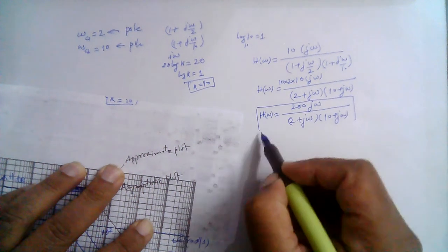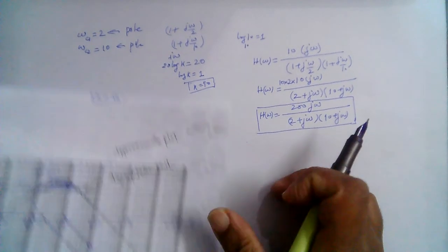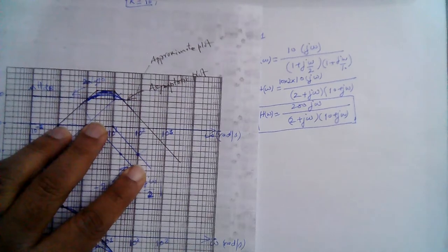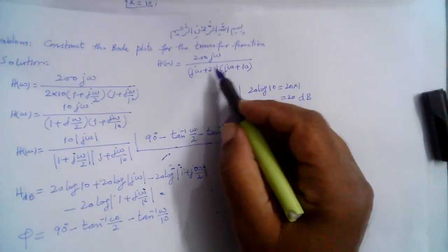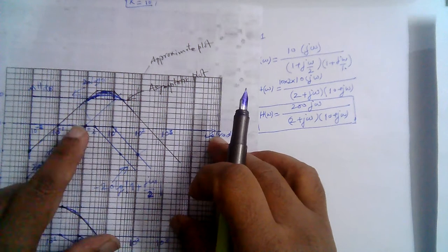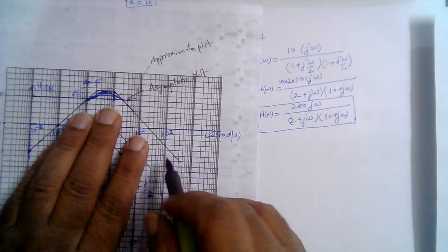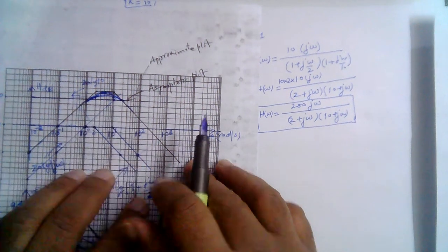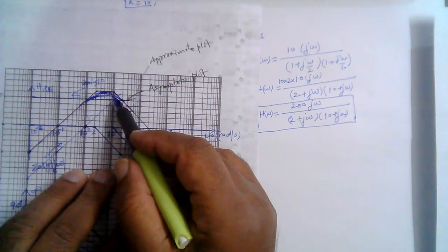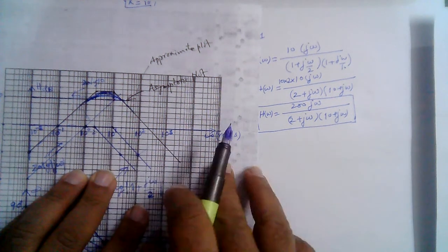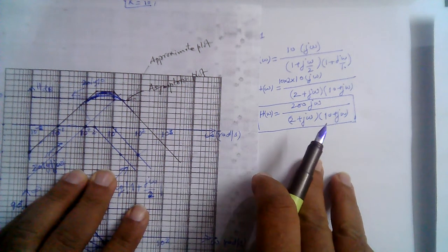So, given the magnitude plot, we can infer the transfer function. This is the same transfer function that we were already provided with. We found the transfer function from the magnitude plot. So given the magnitude plot alone, the composite plot, we can figure out the transfer function as well, by noting down the corner frequencies. With the help of the corner frequencies, we can find the transfer function from the magnitude plot as well.